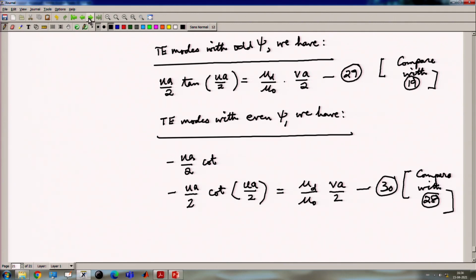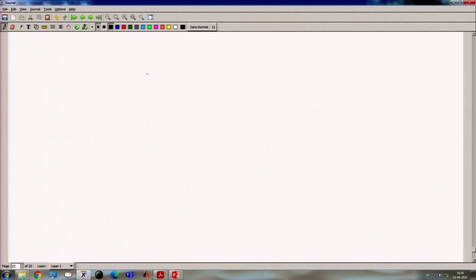So, for the TE modes, the fields are obtained from the Psi's by the equations which are exactly dual to equations 4 that are relevant for the TM modes. We have already derived those equations, but these equations are for del del y equal to 0 and del del z equal to minus j k z as we did for the TM modes.